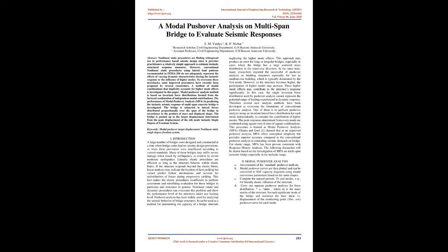Linearly elastic procedures are efficient as long as the structure behaves within elastic limits. If the structure responds beyond the elastic limits, linear analyses may indicate the location of first yielding but cannot predict failure mechanisms and account for redistribution of forces during progressive yielding. This fact makes the elastic procedures insufficient to perform assessment and retrofitting evaluation for those bridges in particular and structures in general. Nonlinear static and dynamic procedures can overcome this problem and show the performance level of the structures under any loading level. Pushover analysis has been widely used for analyzing the seismic behavior of bridge structures.